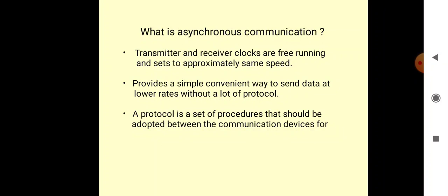Okay, parallel data transmission specifies that in this transmission, n wires are used to send n bits at a time. That way, each bit has its own wire, and all n bits of one group can be transmitted. So, for example, if we are having 8 bits, 8 wires are bundled in the cable with a connector at each end.